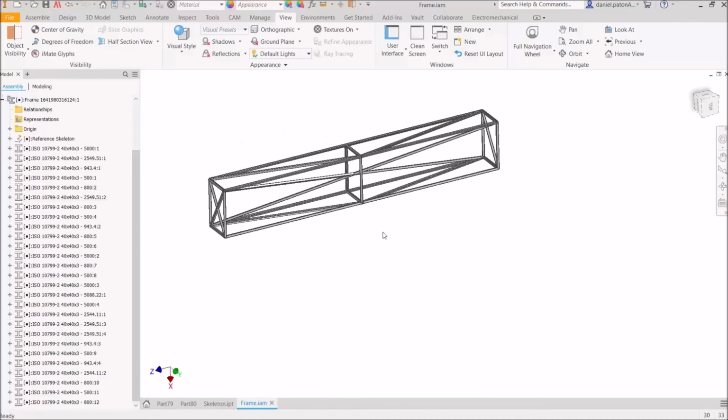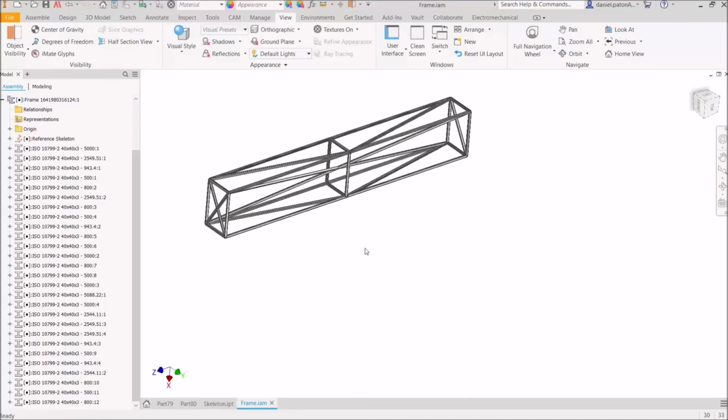Okay, so again, my word of advice is the better way to use 3D sketches, personally, I think, will be if you have some anchoring points that can be easily controlled from work planes or from 2D sketches. Okay.